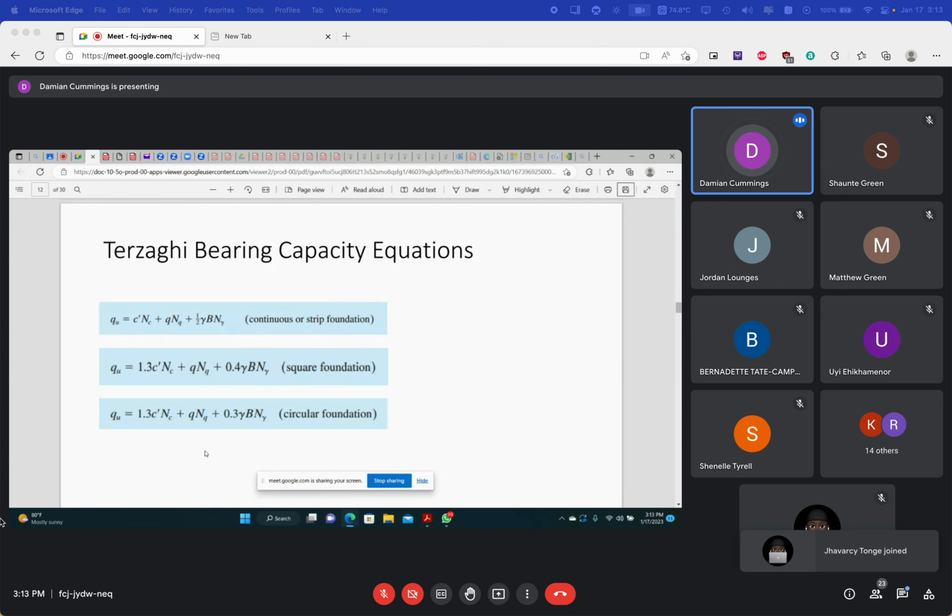This q is the stress acting at the bottom of the foundation from the soil, the imposed load from the soil above the bottom of the foundation. And this q is equal to gamma times the depth of the foundation. So it's the unit weight of the soil times the depth of the foundation that gives you q. When we are doing bearing capacity, that's what it represents.